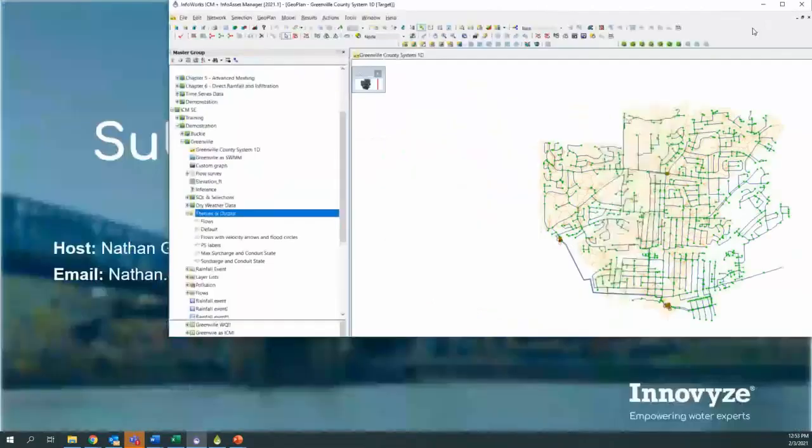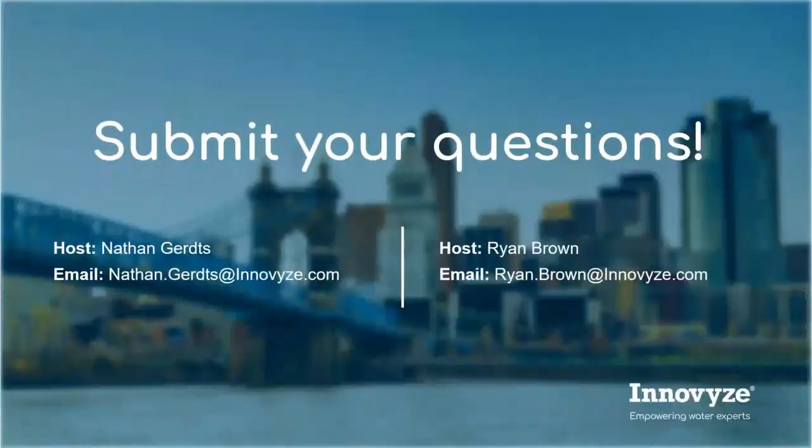Okay. Are there plans to add explicit features such as nodes or link types for green infrastructure/LID, as opposed to applying SUDS or SUDS controls to subcatchments or similar? Yeah, good question. In the SWMM modeling world, we're used to applying LIDs within subcatchments. In ICM you can use that approach, SUDS or LIDs on subcatchments, but you can also incorporate green infrastructure within the 1D network itself.